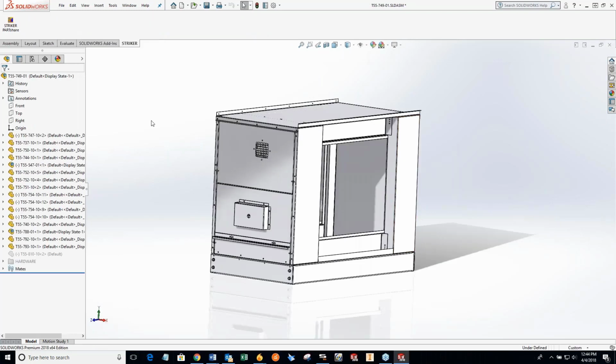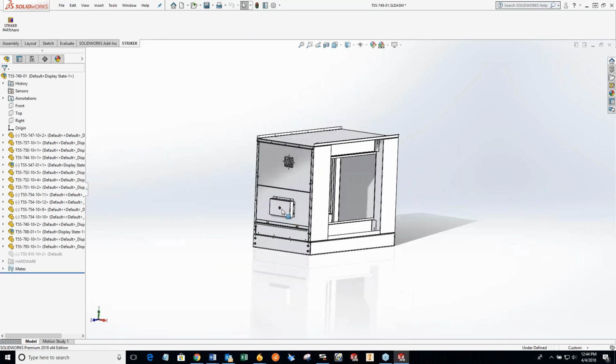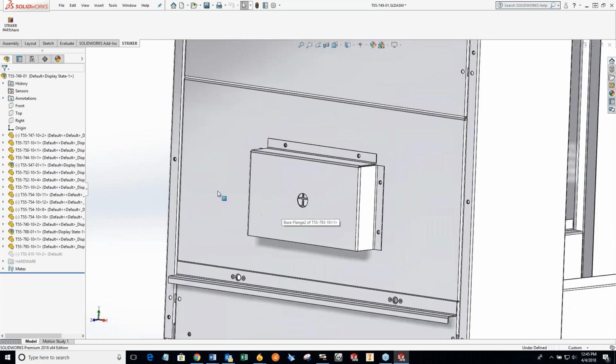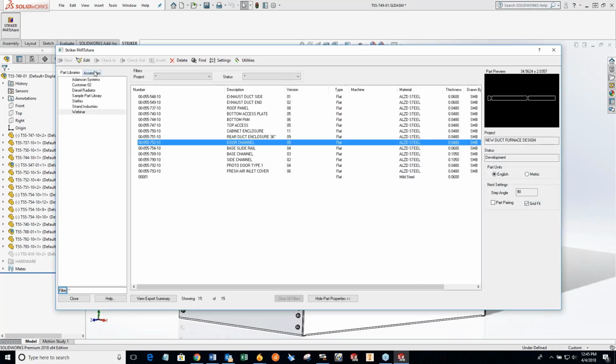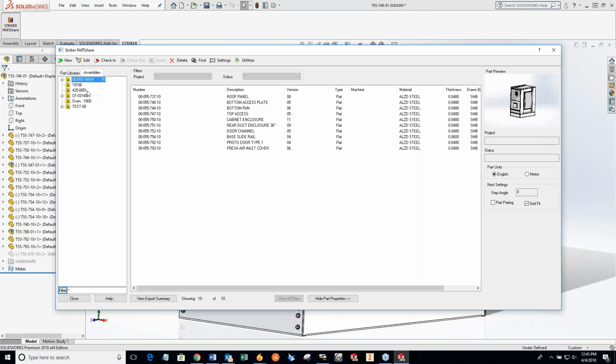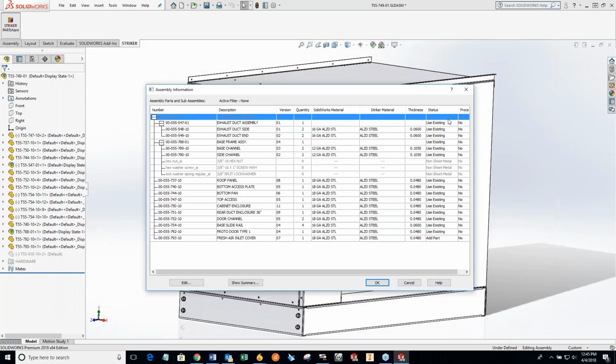Now, there's been a revision, so we see that revision is now a part of our assembly. So obviously the assembly would need to be re-extracted or re-pushed out there if there's been any revisions made to it. But if we watch this, if I go back into PARTshare, I have the option now, just like we did a check-in from within the Stryker CAD CAM environment, I can go to that assembly and say, well, I need to check in, and you'll notice that it recognizes that all of these parts are fine, with the exception of one that has had a new revision assigned.